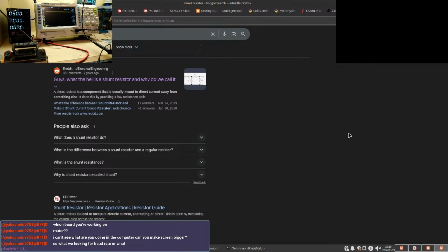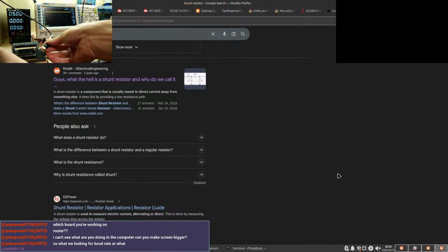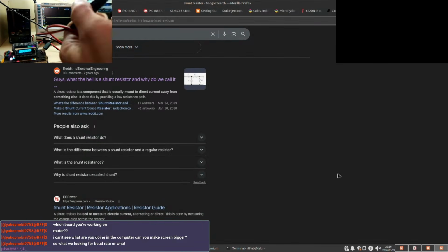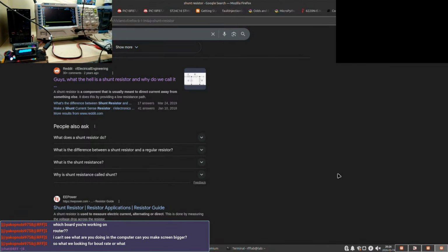Because if I have an external circuit, I'd have to either have two separate grounds, one for the jumperless and one for the external circuit, or I could bridge them? I don't know, that seems like trouble. Let's power it from the jumperless itself. We won't use the external power supply. Let's use the jumperless power supply, and then we don't have to worry about it, because that's the recommended way to do it.